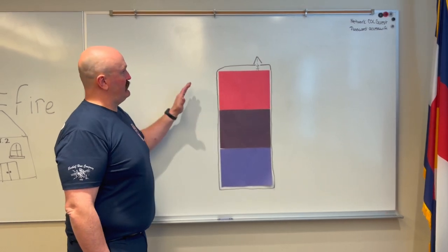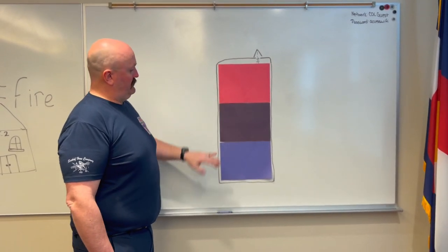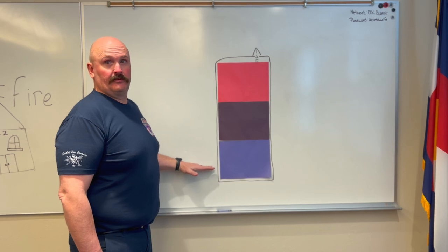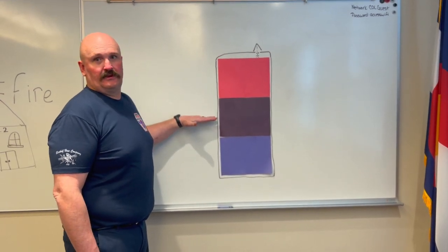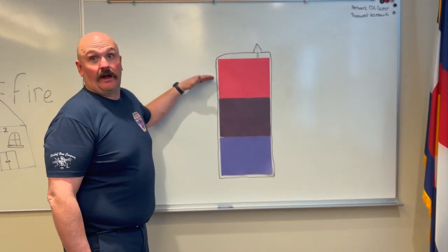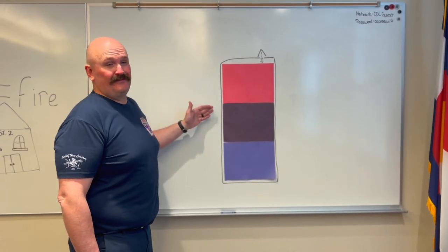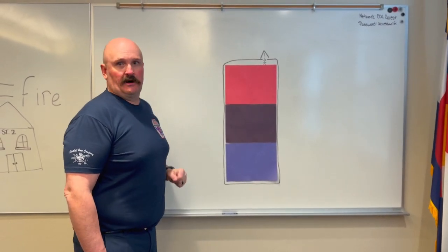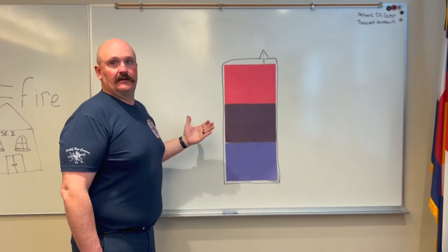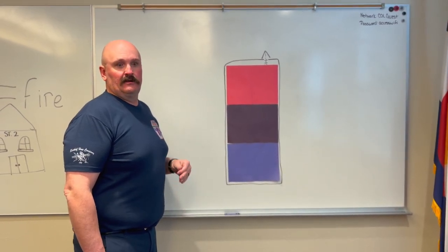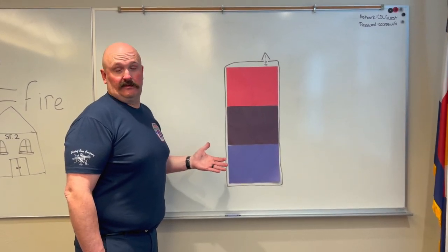So we would have remote monitoring with tubing for the bottom 1/3, then tied off for the middle 1/3 and the top 1/3. And we would have those monitors running the entire time in conjunction with the personal monitor that the technician may wear with any entry team.